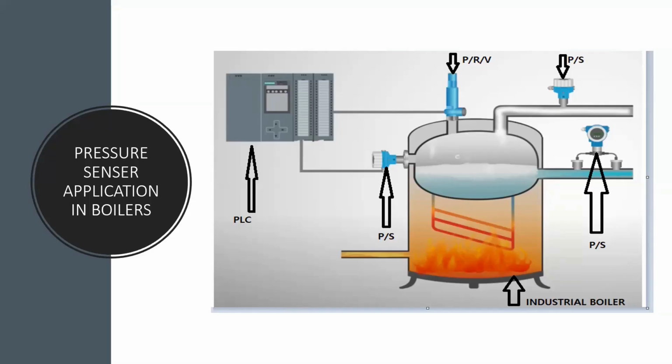So when the pressure sensor senses steam pressure more than required, whereas our intention is to send just about 5 bar to the destination machine, meanwhile the ability of the boiler is 8 bar, then we can tell the controller, when you see a pressure of about 8 bar, what you have to do is close the modulating valve about 75% so as to reduce the pressure of steam sent to the destination machine.